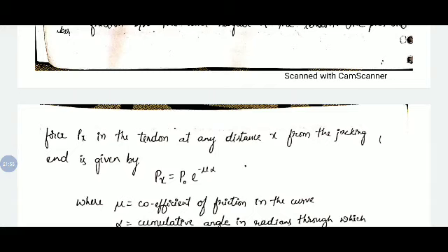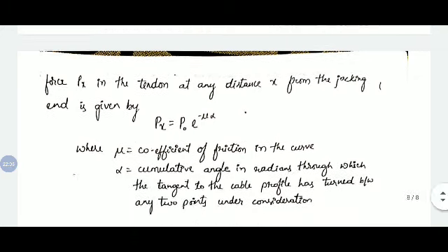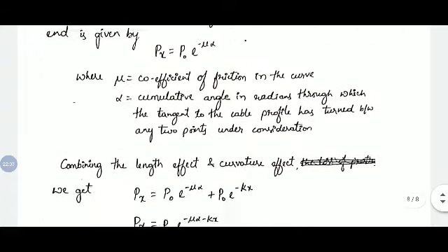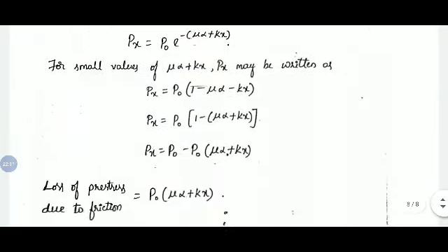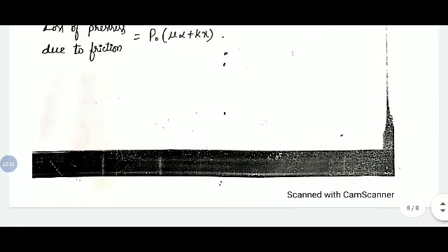So because of that, there will be some contact between the tendons and surface of the concrete. Because of that reason, again the friction develops. So because of that, there will be some loss, and these formulas will be available in the code book IS 1343.